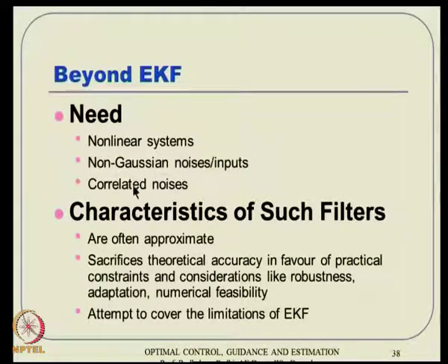So, cross correlation means if I take x1 of t1 and x2 of t1, again at the same time but two different variables, and take the multiplication of that, it also turns out to be 0. But in general it is not so; one has an impact on the other and things like that. So, in that particular case what will you do? That is called correlated noise.